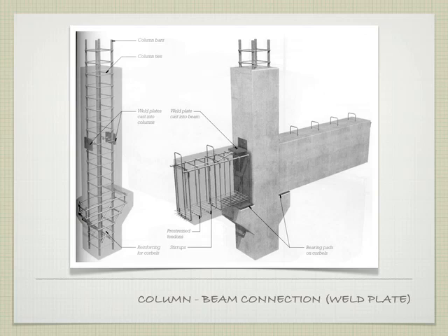Yes. So that weld plate isn't just arbitrarily stuck into the concrete. It's tied into the reinforcing of the beam itself. So we're actually tying the reinforcing to the reinforcing, not the concrete to the concrete. Which should make some sense because what we're trying to tie together is tensile forces. The concrete, by compression, if one is resting against the other, is going to handle compression stress just fine.